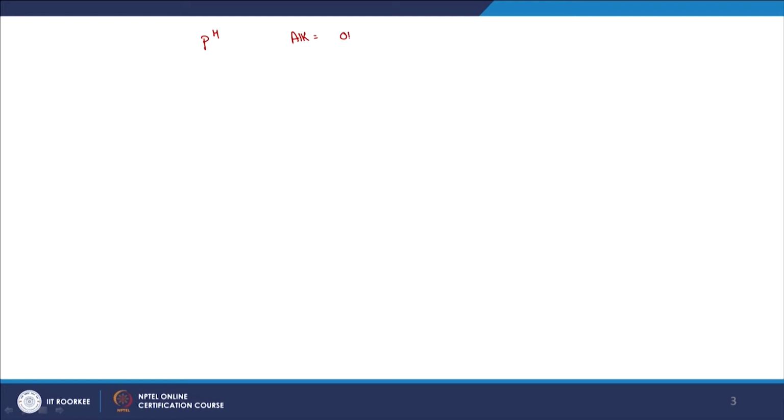So here the key is that I already have pH and I have alkalinity, right. And what is alkalinity now? You know that alkalinity is the acid neutralizing capacity, but here again the key was that only the carbonate species are the relevant species. So we are only going to consider them. So what are all the bases present here? They are OH minus, plus HCO3 minus, plus 2 times CO3 2 minus, because it can neutralize 2 moles of H plus, and obviously minus H plus.